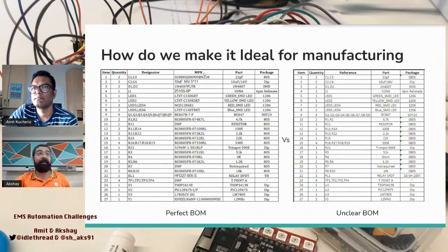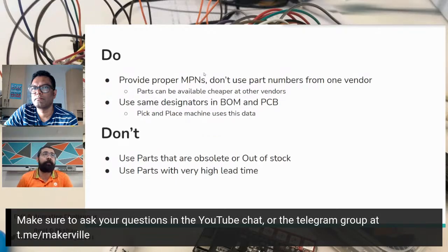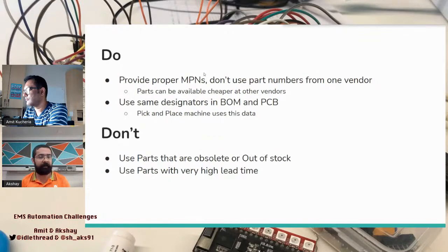So moving on to having a perfect BOM, let's look at what we really need to do to get your component sourcing right. You need to be clear on what your manufacturer part number is. Make sure you don't use your own; every shop will put their own SKU on it. If I want to call this 100 ohm resistor, let's say, PCBK 123, when I try to source it in the market, it's not going to be easy for me to find. The manufacturer part number is unique. We should keep using that.